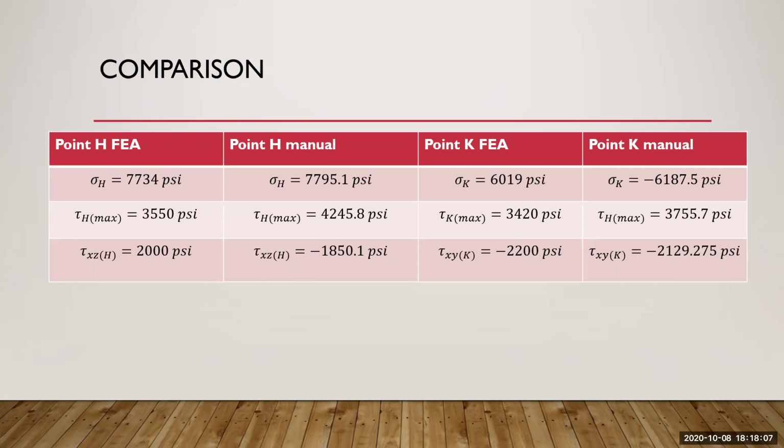But anyways, it was a good project because I was able to determine the differences between the hand calculations using von Mises theories, as well as minimum and maximum principal stresses theories, and then replicating the same thing on NX Siemens, which is the CAD program tool.